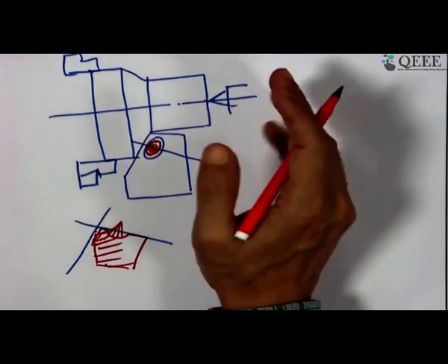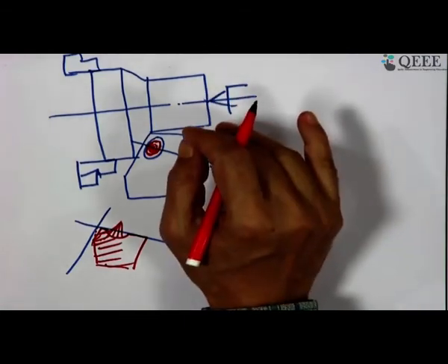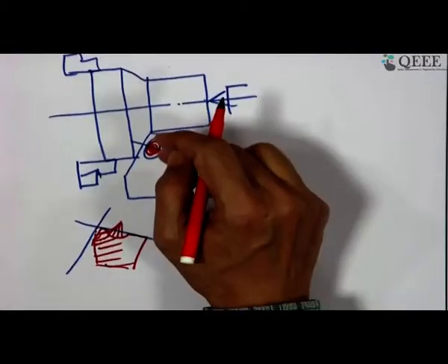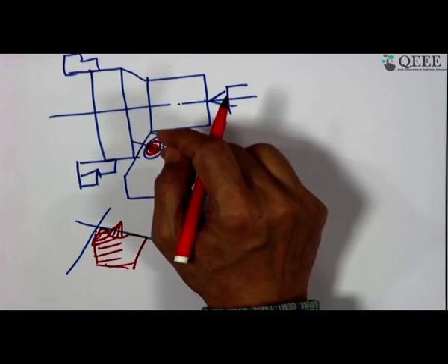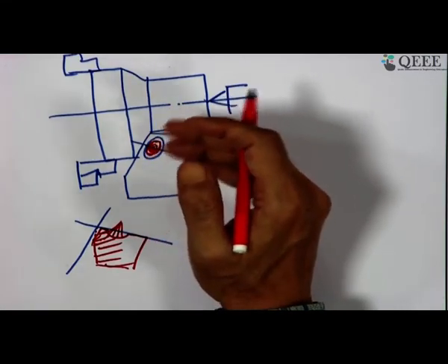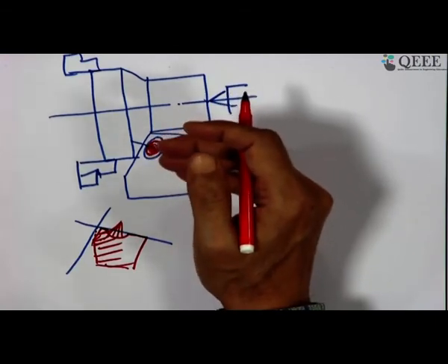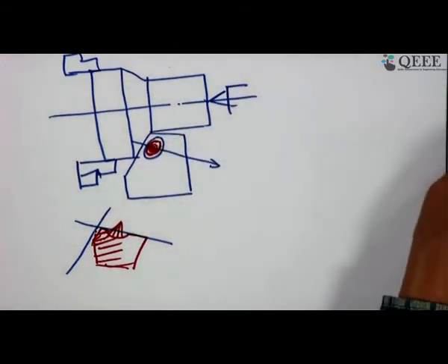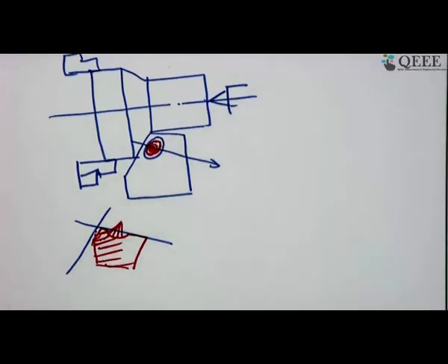Now, in most of the cases it is the flank wear which decides the life of the tool, and it is not the case where crater wear dominates, except where the wear is temperature sensitive wear, which is chemical reaction or chemical dissolution. Here one point one has to record.